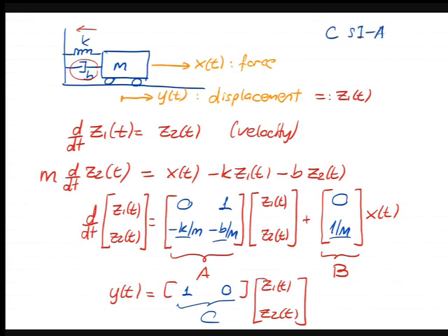So you can on your own, I'm running out of time, do this multiplication. C times (sI minus A) inverse, multiply with B, that's going to give you the transfer function. You're going to get a second order transfer function. Ask yourself, this is not homework to be graded, but something you should do on your own. Ask yourself when these two poles are actually complex, when you have actual resonance, okay? And then try to write down these conditions.